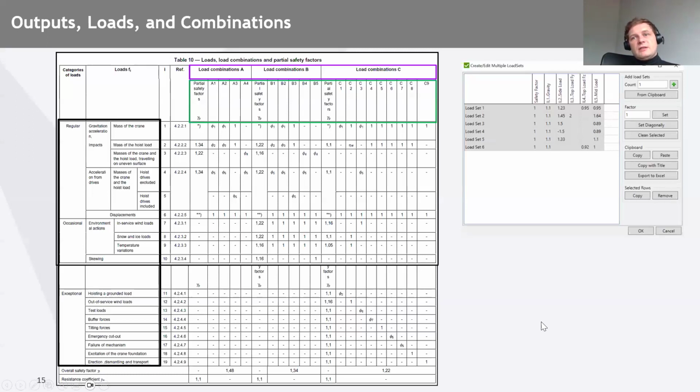And these are defined by standard, while SDC Verifier is allowing to build loading combinations to take into account all of the possible scenarios. So when you are going to review your results, it's not only under a specific loading condition, but multiple loading conditions. Some of our customers are generating hundreds of loading scenarios, especially if you're speaking about the structure which is subjected to environmental loads like winds and waves, where you have basically all possible combinations from all directions. It ends up with hundreds of loading combinations.